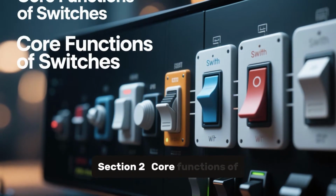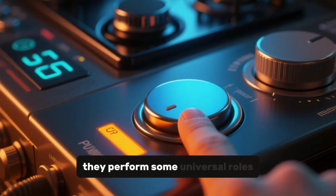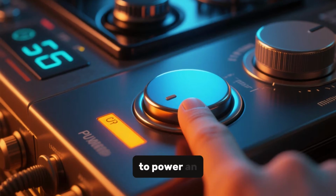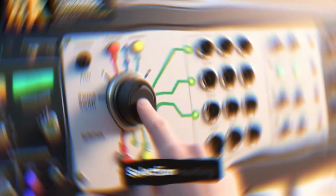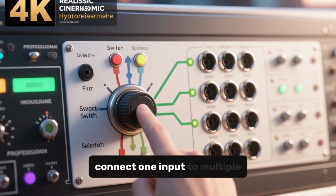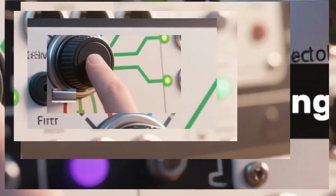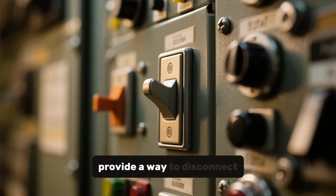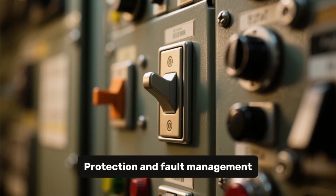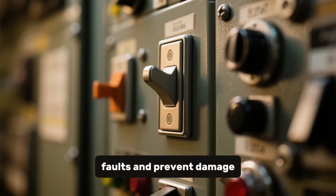Section 2. Core functions of switches. Even though switches come in many forms, they perform some universal roles. On-off control: make or break a circuit to power an appliance or subsystem. Selection/routing: choose among multiple circuits or connect one input to multiple outputs, e.g., changeover or multi-position switches. Isolation: provide a way to disconnect equipment for safe maintenance. Protection and fault management: used with relays and breakers to disconnect faults and prevent damage.